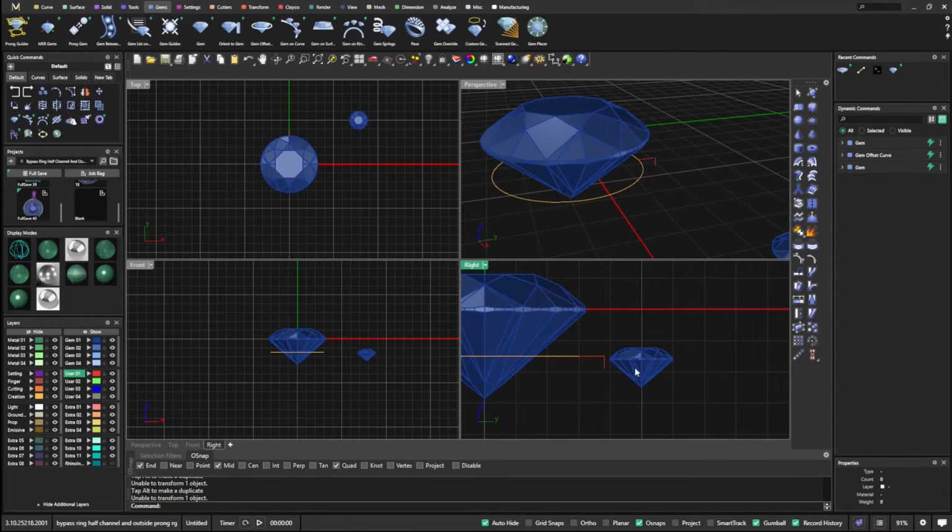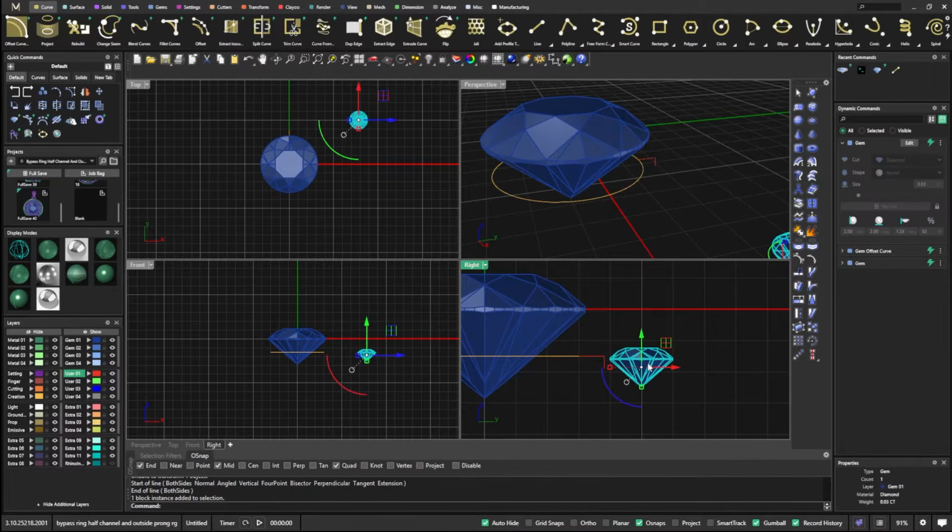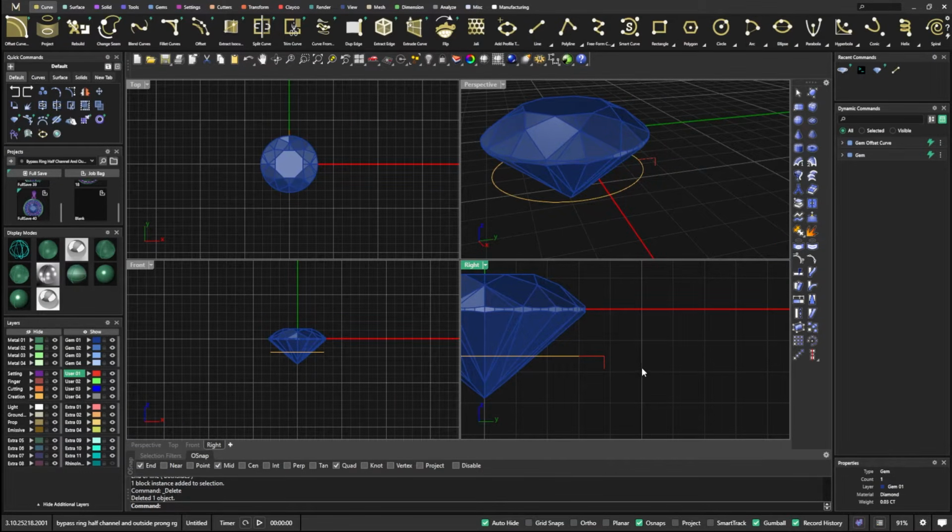So you can use a gemstone, and then we could grab a line curve, click here, and go over to see where you want that other side, right? You could do it that way, or if you know it's going to be 2 millimeter, you need maybe a little extra meat on each side. So we'll click here and type in 2.2.